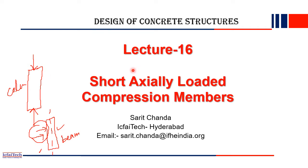In this lecture we'll be discussing how to design a short axially loaded compression member. Again, as discussed in the last class, there are two types of column, short column and long column, based on the length of the column. If the length of the column is very high, the failure of the column will happen because of buckling, not because of crushing of material. Whereas if the length of the column is very short, then the failure will happen because of crushing of material, not because of buckling.